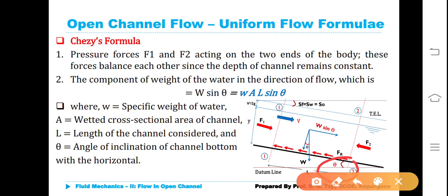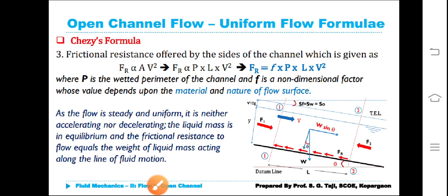That is equal to small w A L sin theta, where A is cross-sectional area, L is the length between section 1-1 and section 2-2, where small w is specific weight of water and theta is the angle of inclination of channel bottom with the horizontal, that is datum line.